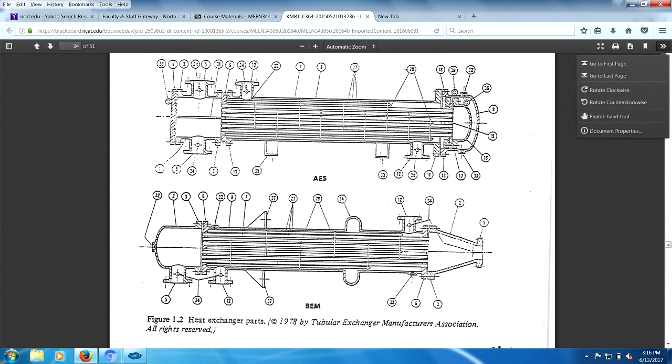Second hold point is you have a tube sheet sitting here. There's a tube, and it's a sheet of tubes. You want to watch how the tubes are inserted into the tube sheet. There is no pounding with a hammer. The tube opening should be free of burrs and there should be no lubricant used.